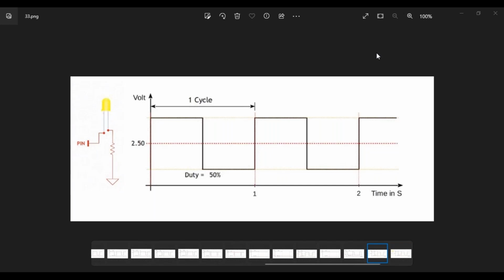Okay. So that is how the pulse width modulation is actually achieved in order to maintain the average power which is being delivered to that particular load. So with the help of pulse width modulation, if I have to summarize, pulse width modulation in fact is a technique of varying the average power delivered to the load by varying the duty cycle of a particular pulse.